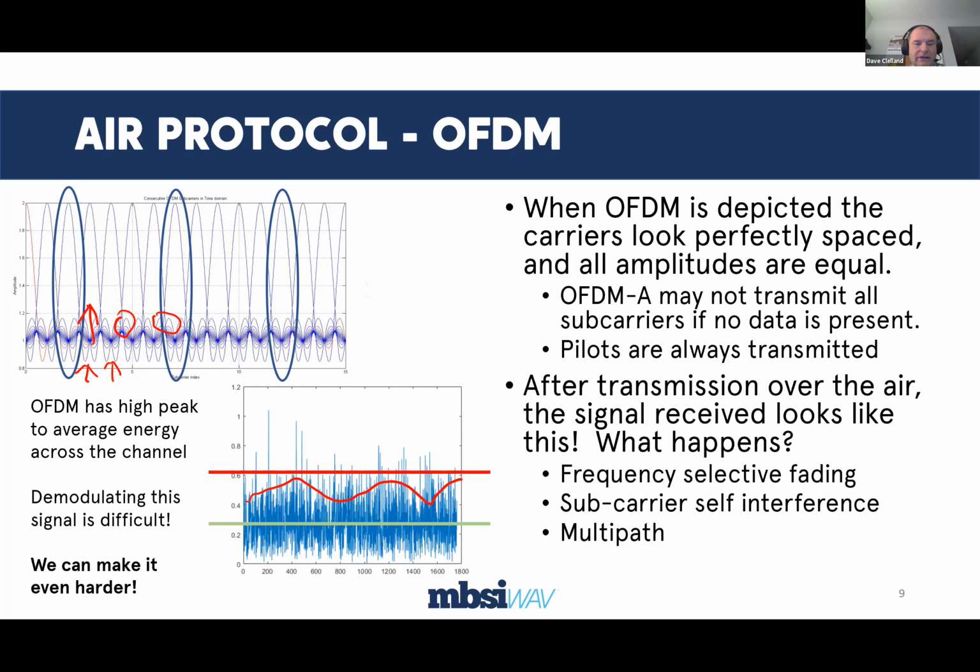So we have this business here where the adjacent carriers are placed where the second harmonic would normally be, which is normally negative. So the third and fifth harmonic are values that add to the signal. The second harmonic and the fourth harmonic are values that take away from the signal. So what a great place to put the adjacent carrier beside it.